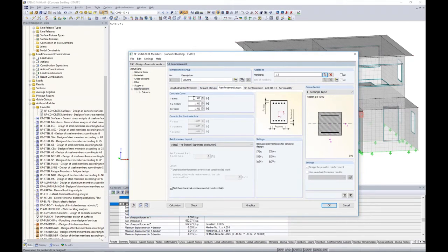The reinforcement layout. The first thing to set here is the concrete cover. The ACI standard refers to table 26.13.1 for concrete designation, and for number 5s or smaller that are exposed to weather, the code tells us that 1.5 inches is adequate. So assuming we're using number 5s here, we'll just keep this as the default of 1.5 inches. If the program came up with number 6s for my reinforcement, well, maybe I'd want to go back and adjust this to something more like 2 inches.